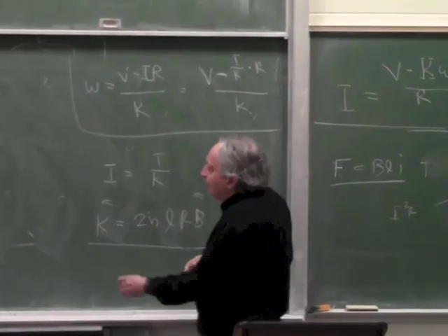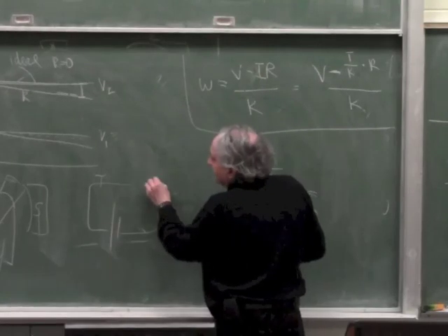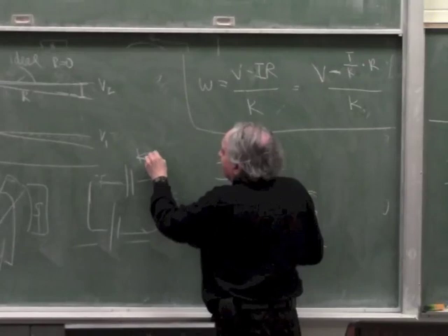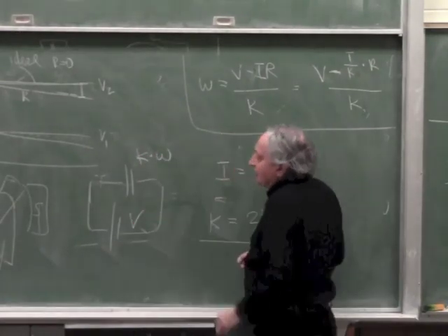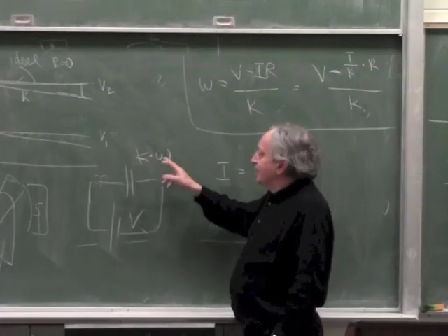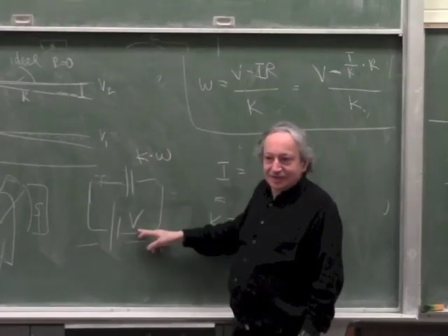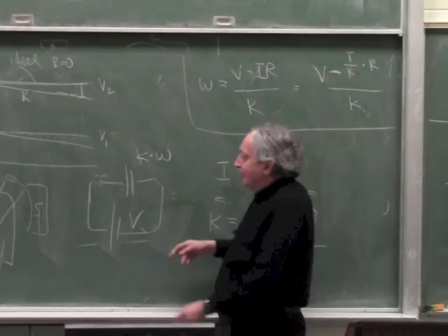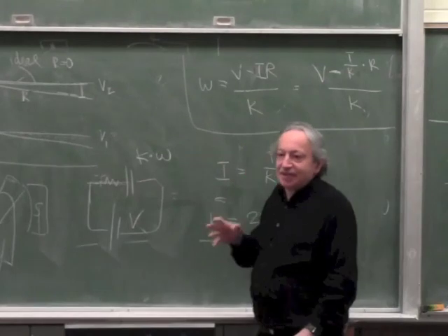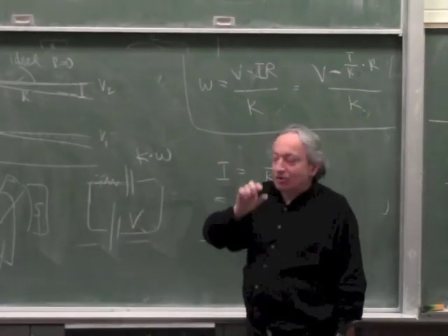Because if we look at a simplified motor, it is a battery and a back EMF, and this is simply K times omega, and this is V. If I make K bigger, omega is slower to match the V. Is that clear? The motor also has a small resistance, but the resistance doesn't really affect the answer much, because the resistance IR is small compared to V.